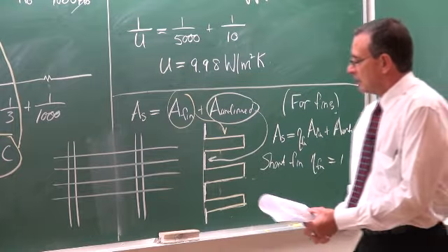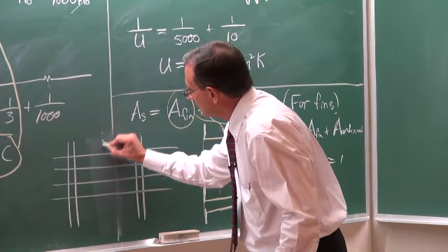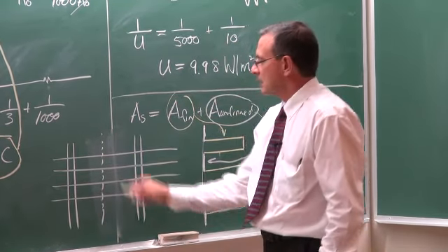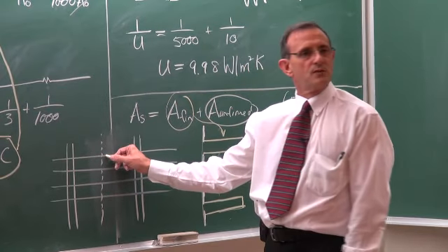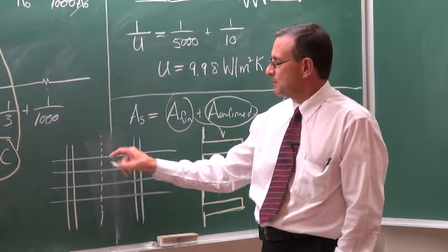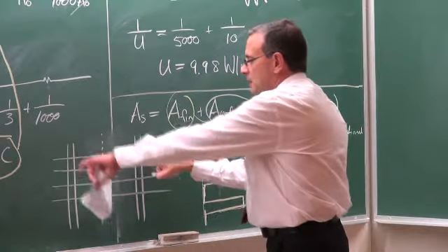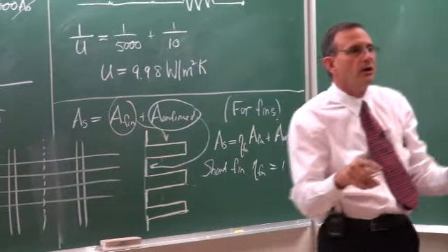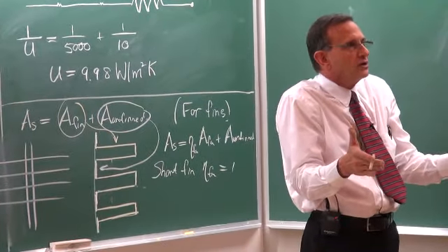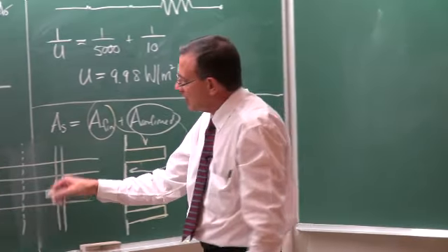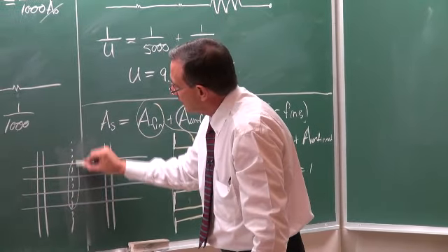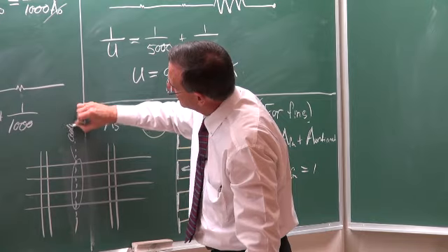For that case, if we look at the center line, the temperature here would be approximately equal to the temperature there, especially if the temperatures in the tubes are the same, which happens in condensation or evaporation. Therefore, those fins would be adiabatic fins.